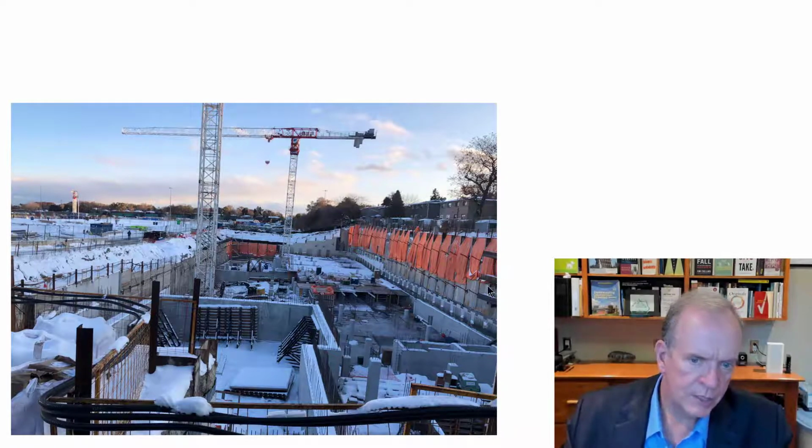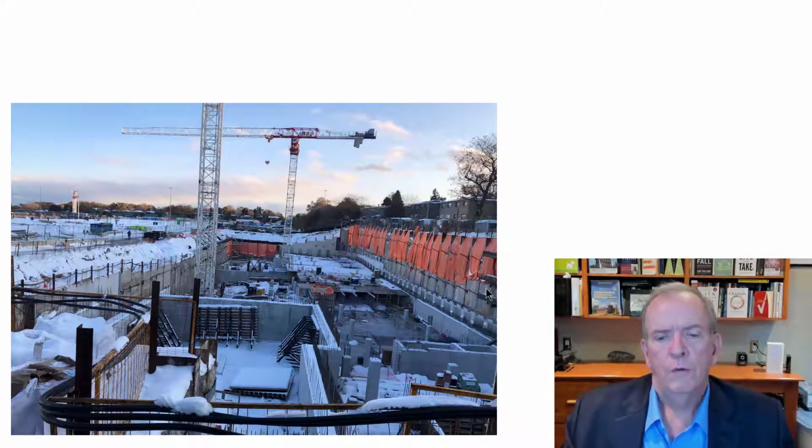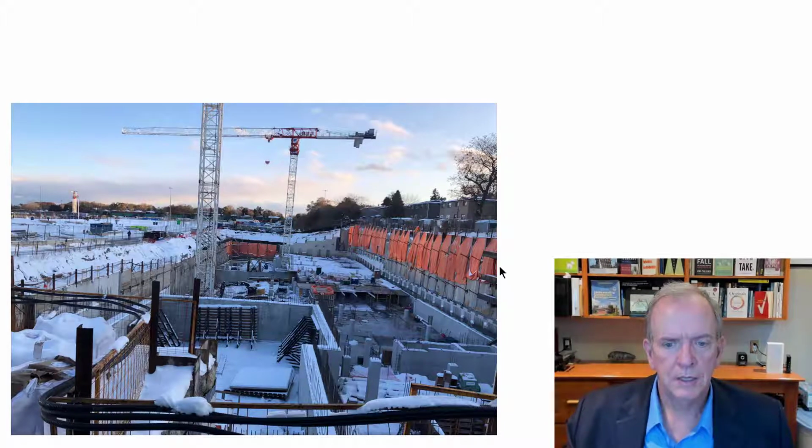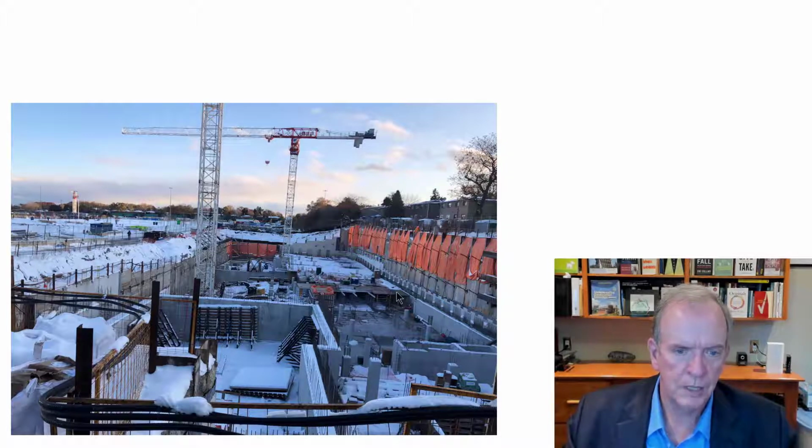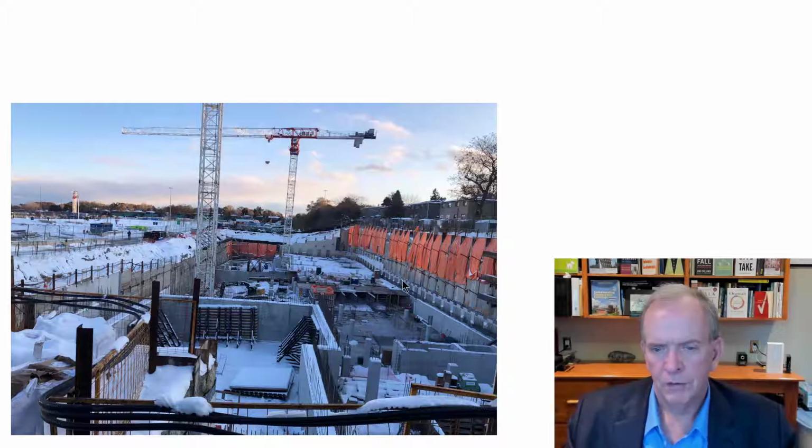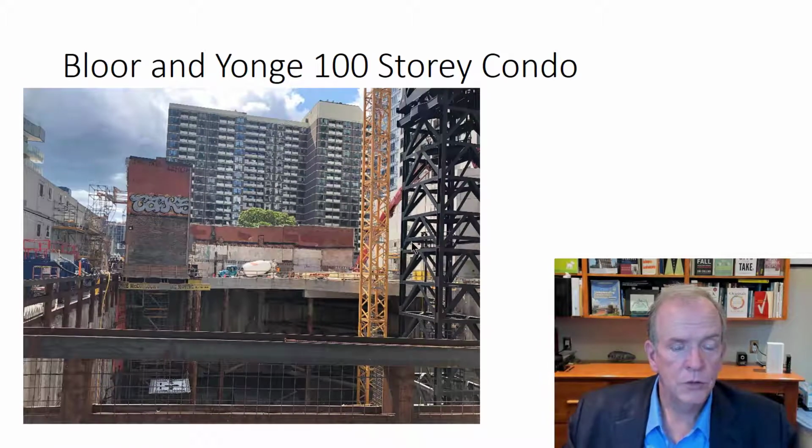All right, this one section here, you can't really see it that good, but there's rakers going along. Well, for one section of one property, I'm assuming they didn't get permission, so they had to put basically these rakers to secure this, and they're basically tied to the ones where they had permission. So it's kind of a short section, one property in width. I think they're about 40-foot lots wide, so probably about 40 foot. Here, there's no permission. You've got other buildings here, you've got other buildings there. There's no permission, so you can't be puncturing the side of another building.